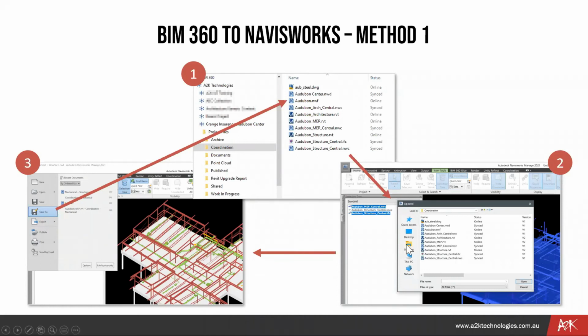From here, despite using the BIM 360 located models, we can then go through and save our Navisworks project file as an NWF file and save that back up into BIM 360, again using the desktop connector. So we've got locally stored model files, we append them into Navisworks, and then we can save the NWF project file back into BIM 360 so that we can open up the NWF file in the future if we would like to continue working on this project.